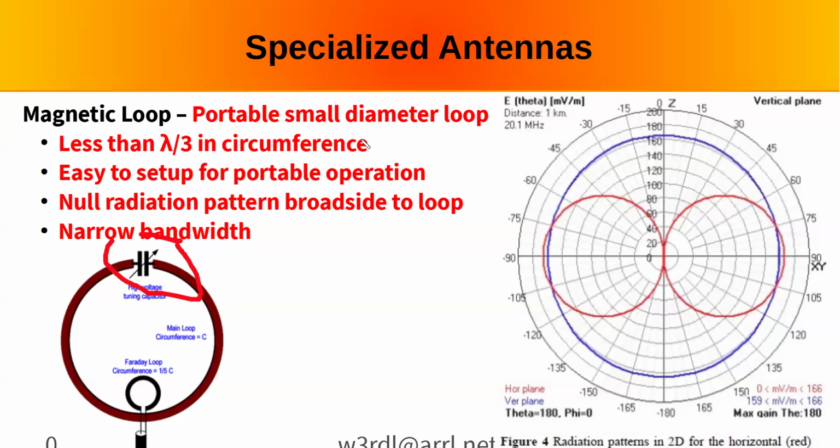And you have to have some way to vary that capacitor, and it has to be very high voltage. You're talking about the ends of those elements, so several thousand volts potentially. They're usually expensive capacitors, vacuum type, and that's one of the reasons these things are expensive.